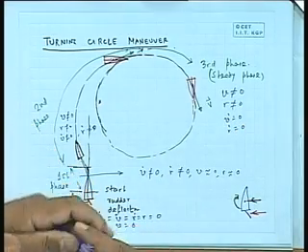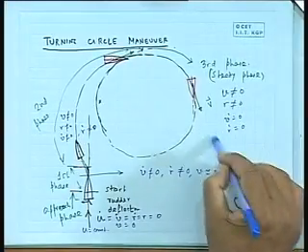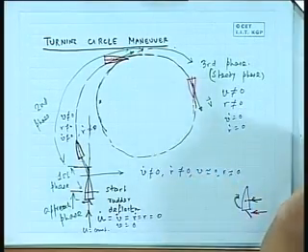When it reaches a steady phase, when it is going steadily like a ship along a straight line course, you must have ultimately no acceleration, because acceleration implies you are changing velocity continuously. Having acceleration implies having forces, but here the force has reached a balance, no more extra force on the system. Like a ship moving steadily, please remember that the net force on the steadily moving ship is 0. T equal to R, the resistance and propulsion just balance, the net X force is 0, T minus R is 0. If T minus R was not 0, the ship would have been continuously accelerating.